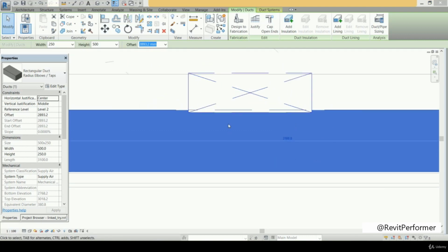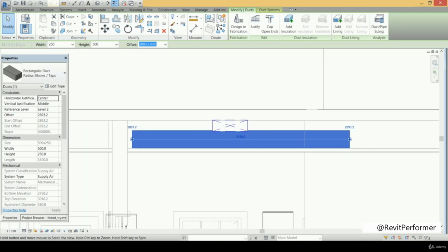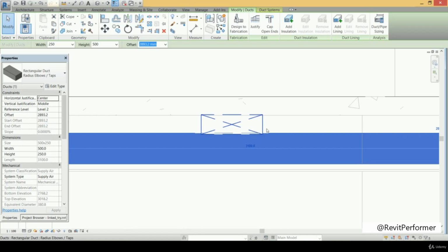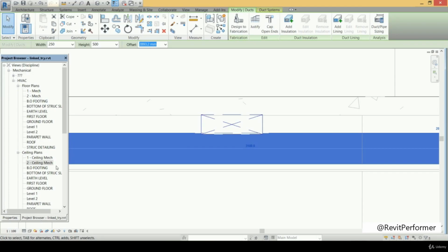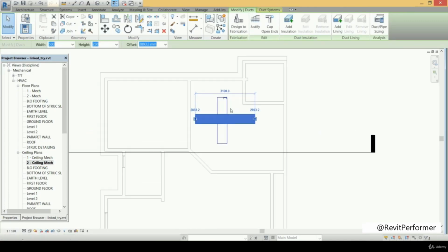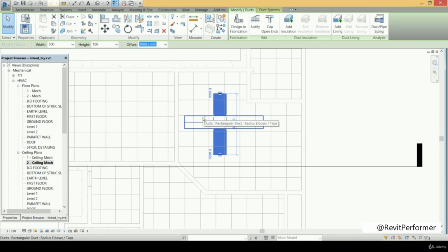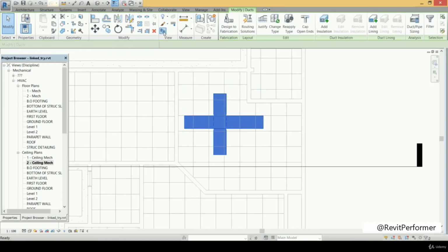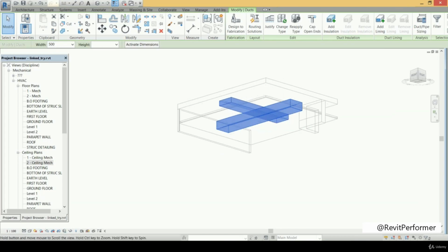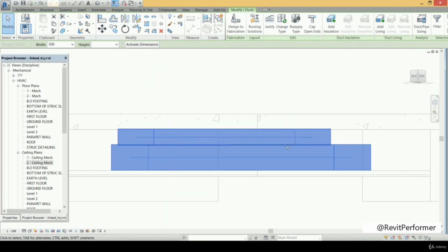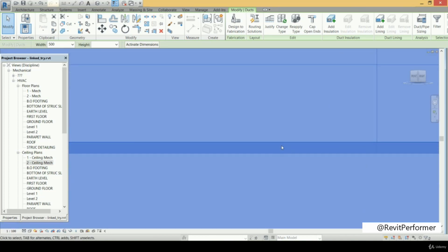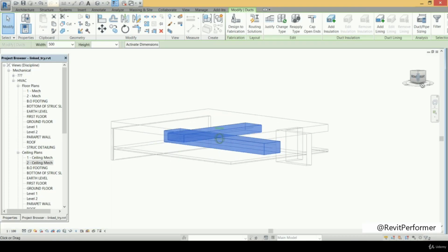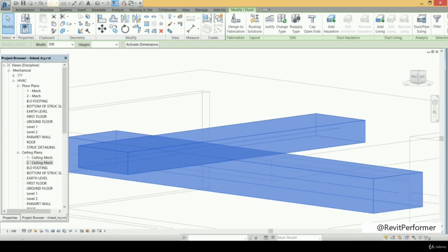And in our case here, or in some practical cases that you may face, there is no way to change the direction of that duct, so it intersects with that duct, and we can see that well in the 3D model. So if we go to the project browser and select the second ceiling again, and then we can select the duct, and here control and the duct, and then we press on the selection box. So those are the two ducts that we have, and here we can see them well. So if we make them at that position, you can see this dark blue area is the intersecting area between the two ducts. And for that, we need to find a solution that will separate those two ducts from each other to make it able for the two ducts to pass through our ceiling.